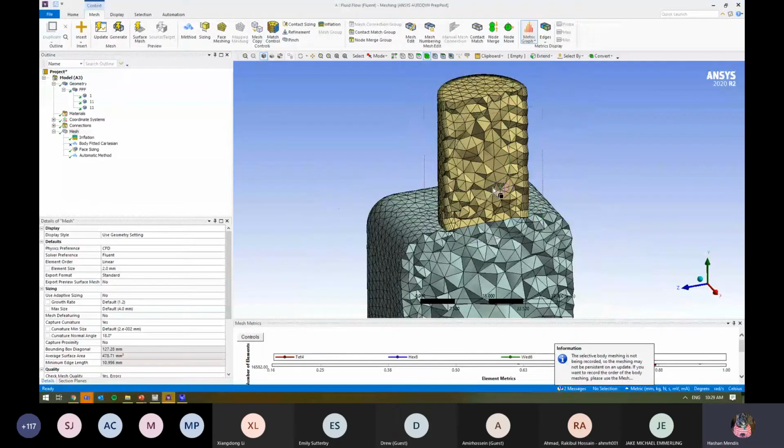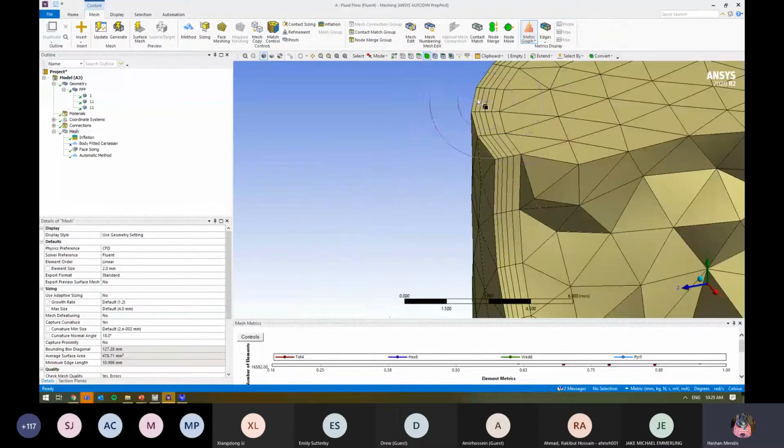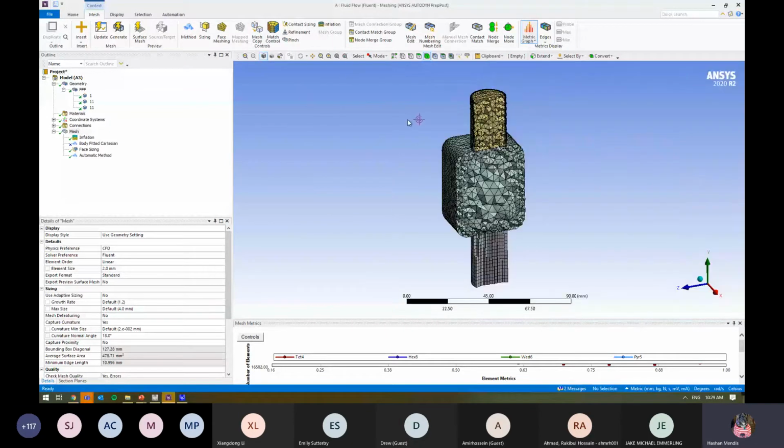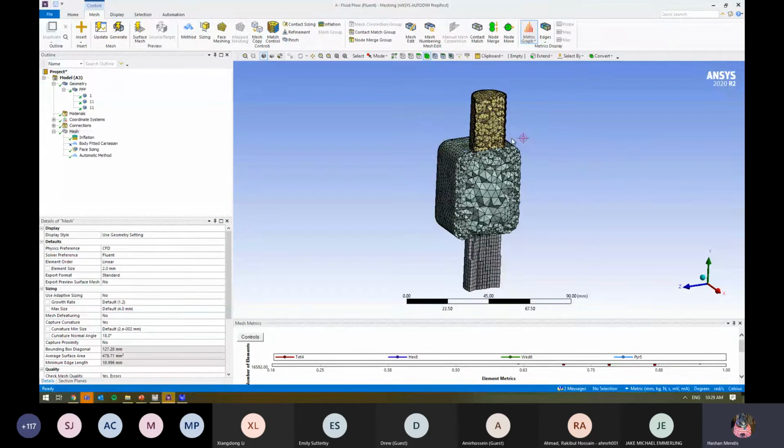So really, it comes back to what is the physics, and what's the physics locally around there as well. Is flow just going in one direction, or do you have things curving in and out? Do you have things protruding and then holes coming through? Is the boundary layer just intact, or does it all of a sudden get tripped up, and we've got turbulence now that we need to account for as well?